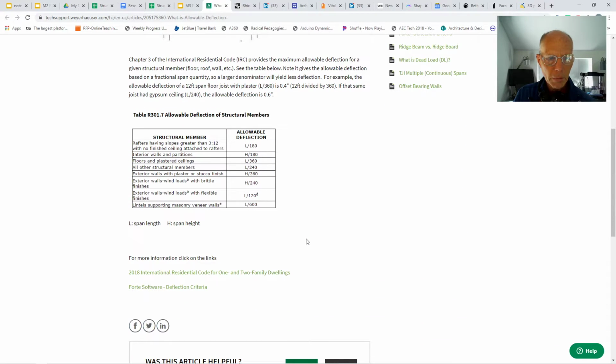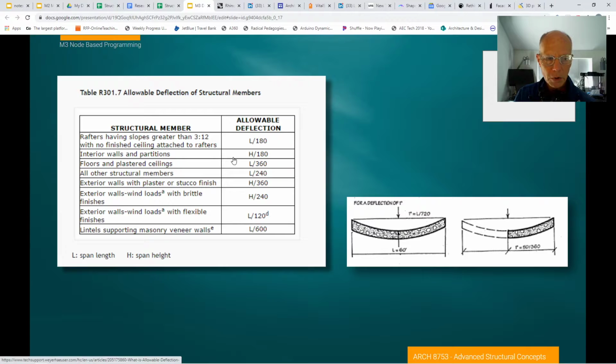allowable from a manufacturer. But this designation here, up here it is, it's from the residential building code for 1 and 2 family dwellings. So it's not a commercial specification, but it's a real good guide about this idea of allowable deflections on surfaces. And these are allowable by code. They don't mean that the client or the performance of the surface would be satisfactory to everyone, but these are the minimums required by code.